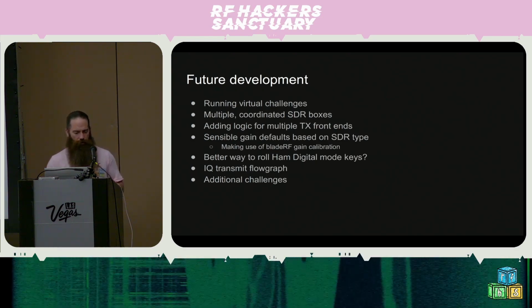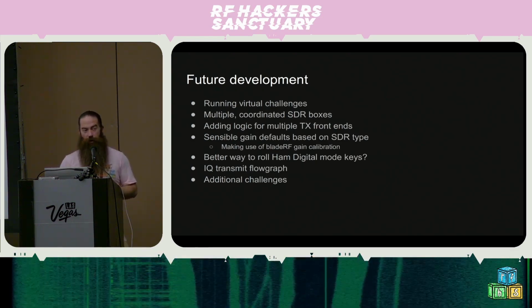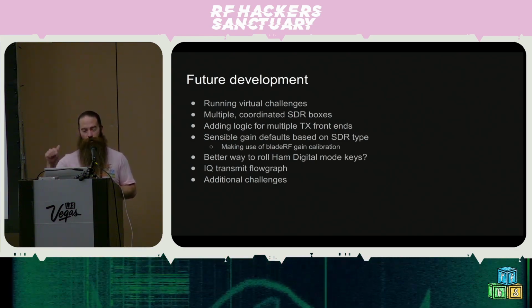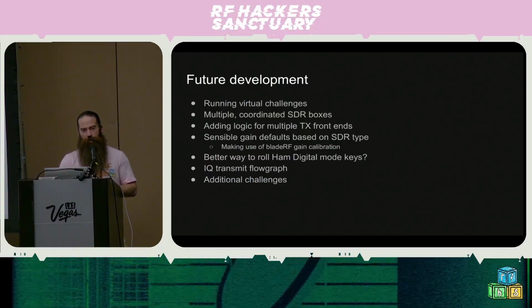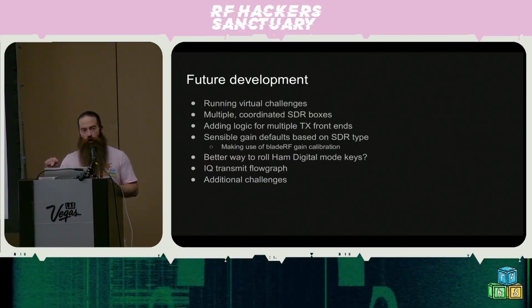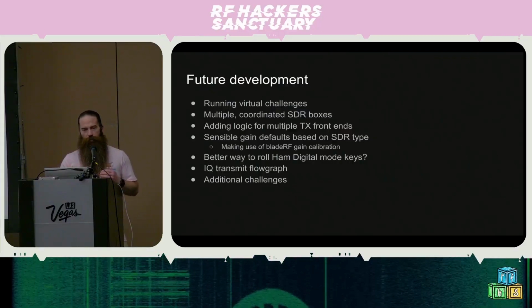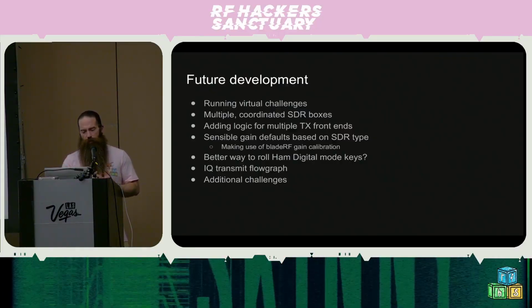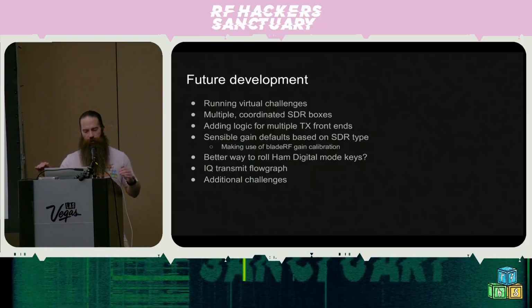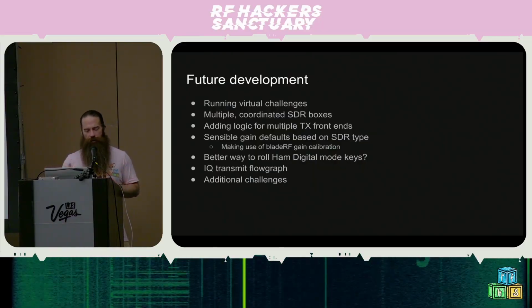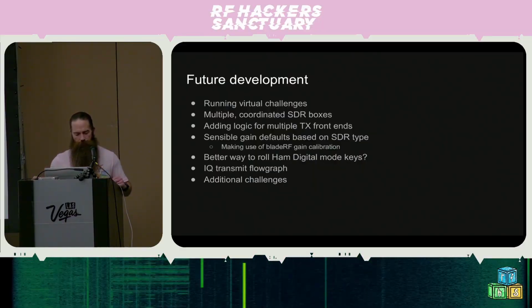I'd also like to make use of the BladeRF gain calibration. So if you have a BladeRF 2.0, Nuand is actually calibrating them for doing a gain calibration. So there is a curve for your transmit frequency and how much power you're actually transmitting. You can standardize that to have it be a flat, consistent gain across the entire spectrum. I think it'd be really cool to have that integrated into Challenge CTL as well.